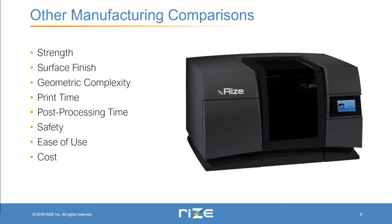Another question is geometric complexity. Each of these technologies is really good at producing a certain subset of geometric complexities. Generally, any 3D printing method is going to be more effective at really complex or organic surfaces than a traditional manufacturing method. Traditional manufacturing methods tend to be better with square or conical types of surfaces. They have more trouble with generatively produced surfaces and things like that. But any 3D printing method can deal with those quite well.